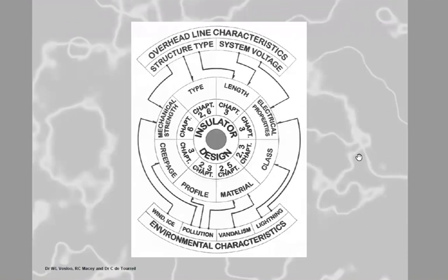You agree? The backbone. And that backbone is most probably the cheapest device when you're building this whole structure or building this line, whether it's in the substation or whether it's on the actual transmission or distribution or MV line. The insulator is actually the smallest costing component in relation to the conductors and the structures and all those things.